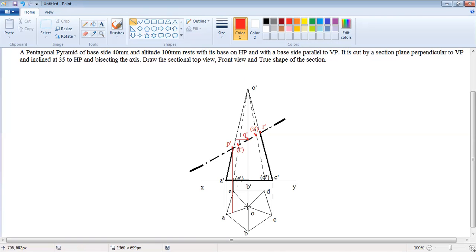Also draw the horizontal line from this O point and extend this Q point to this horizontal line. Place the compass at O, measure this point, and cut an arc on OB.